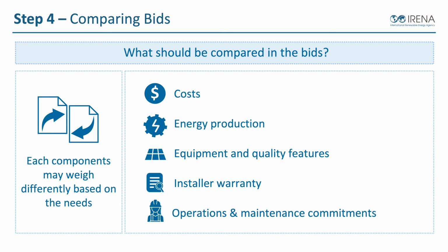And when we do that, we need to make sure that we're looking at the same system types and similar components as well. If one solar contractor gives you a bid and they say, here's a 5 kilowatt PV system that's going to produce X, and another solar company gives you a bid for a 5 kilowatt PV system that's going to produce way more than the other one, we should catch that as a concern: why would these two similar sized systems produce different amounts of energy?